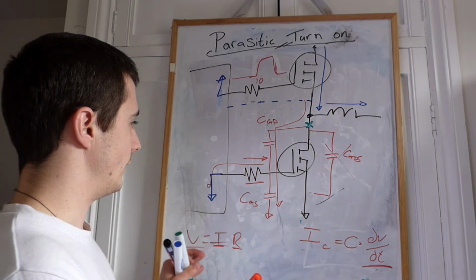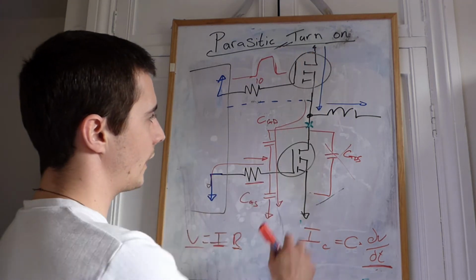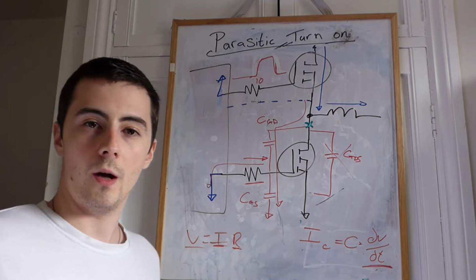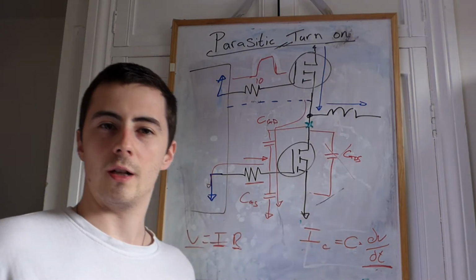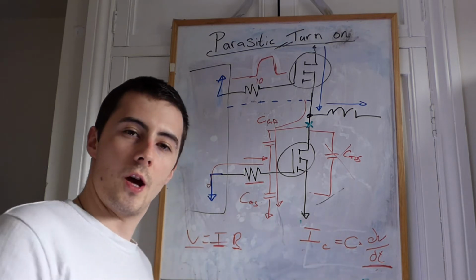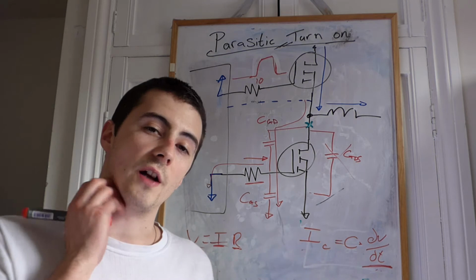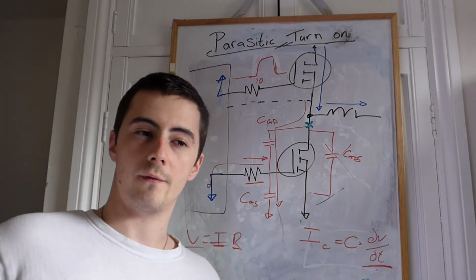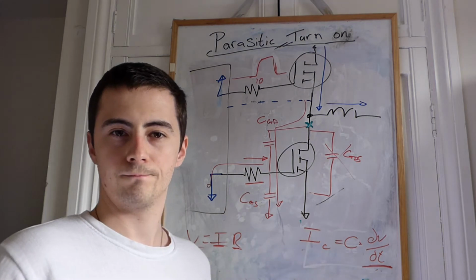So now that we understand the problem, let's take a look at the math. I'll redraw this circuit in a way that's a little bit simpler. We're going to remove the FETs because they're not really needed for the analysis. We'll do some AC Thevenin equivalent analysis of that circuit, and we'll find an equation that we can derive so that we can plot this curve later on.